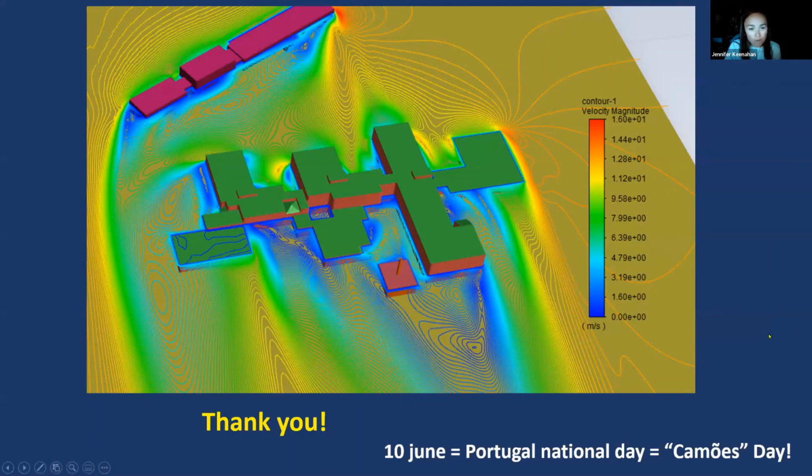What kind of wall function did you use in these models? Roughness wall functions. I'm not sure if I'm being specific enough. So the ground is not smooth. It's roughness wall functions for the k-epsilon model available on ANSYS and on OpenFOAM.